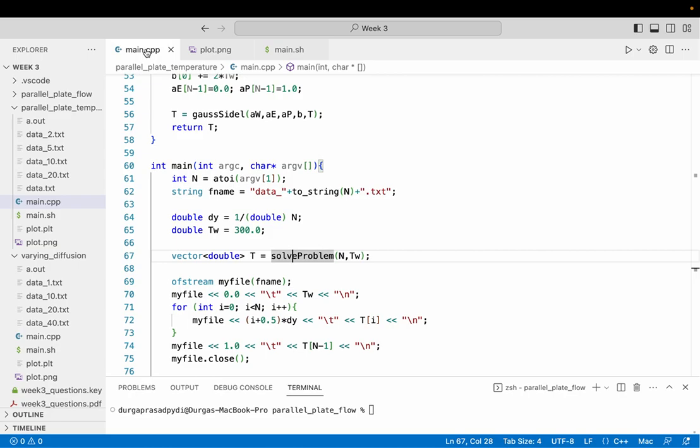But the temperature of the fluid is zero. That's why I'm assuming heat is being added for some time till it achieves constant heat. I'm just asking, since the temperature is constant, you are saying eventually it will reach a case where you have just a conduction profile at the boundary, right? It has to. I'm just wondering why. We'll come to that. That is where you have a thermally fully developed flow.